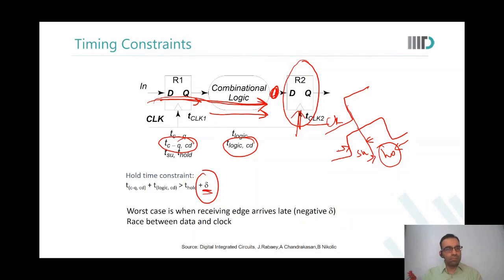So why am I not considering the propagation here and the contamination here? Because of the worst case. But I don't know what my Q will be. My requirement is no transition on the output should have happened, or no transition on input should happen before hold time elapses.